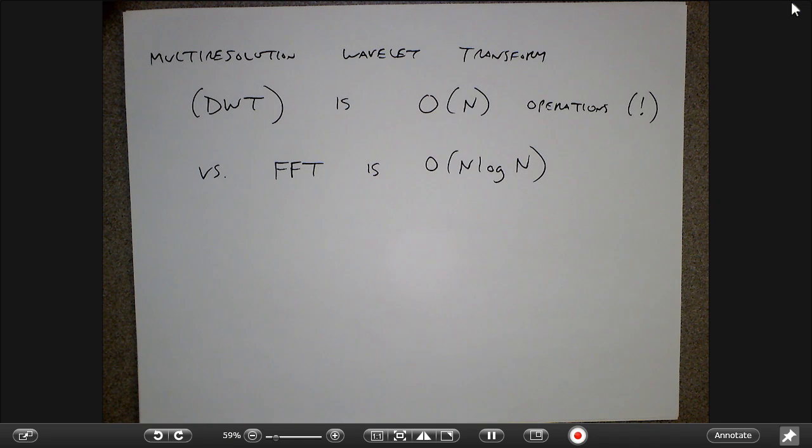For example, if you want a steady light in the room, your eye is not sensitive to changes that occur much above some critical frequency, like 60 hertz. So if we modulate the lights at hundreds or thousands of hertz, we can use that to communicate digital information. And you can imagine that each light in this room might be communicating slightly different information to different people in the room.